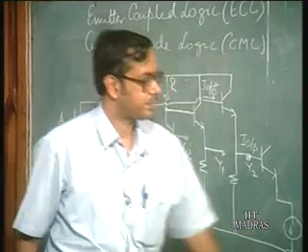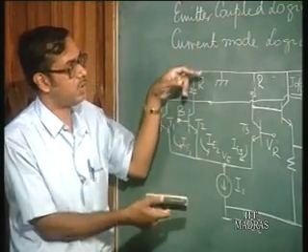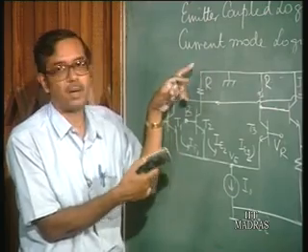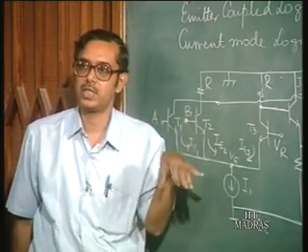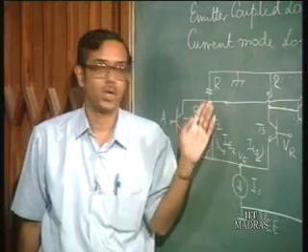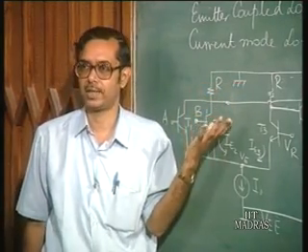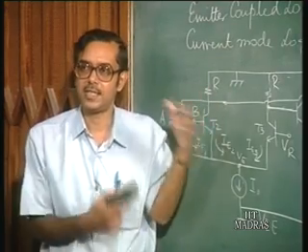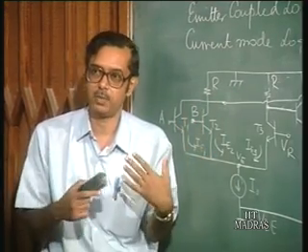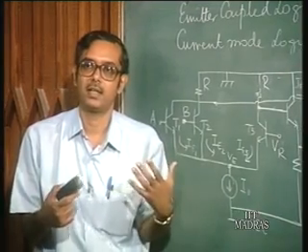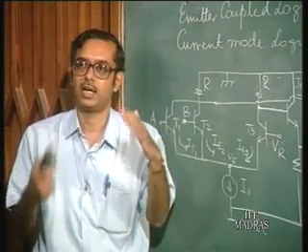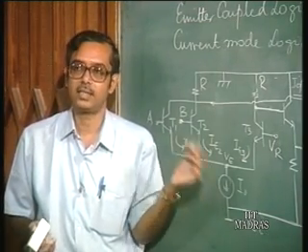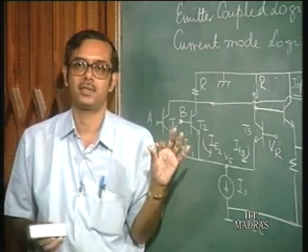Now all this gives rise to what is called power supply noise. The power supply voltage should be a constant, but across the power supply you get some noise when the switching takes place, because these interconnections are not perfect. They have certain inductances. So all these high speed circuits, because of the fast switching, give rise to certain noise across the power supply. The power supply voltages are not dead fixed. And this noise should not affect the operation of the circuit.